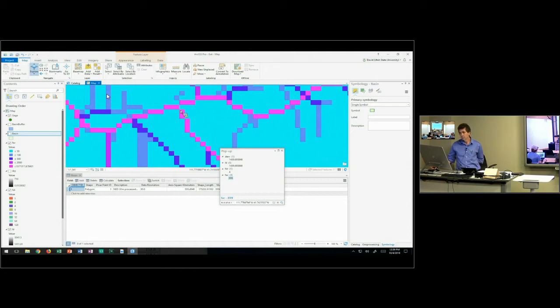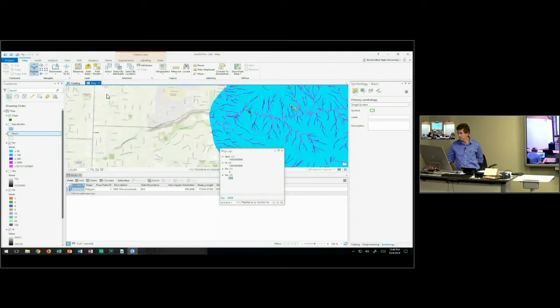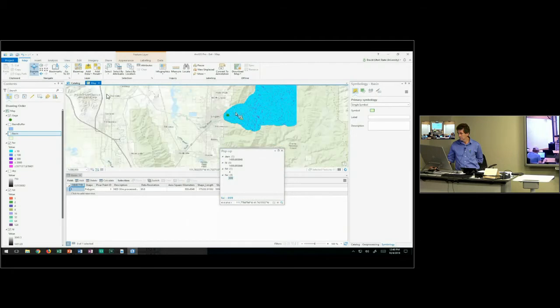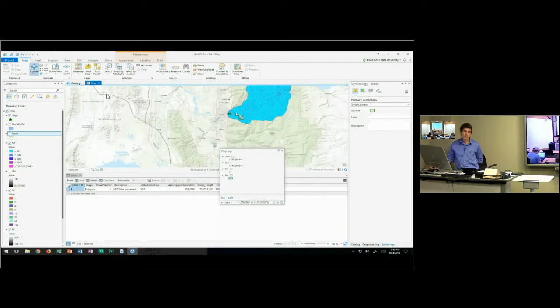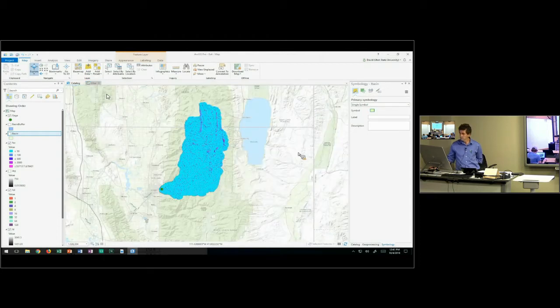This capacity to quickly understand how large the drainage area above a place is, is really, really critical. We have a Texas Medical Center in Houston that got flooded in Tropical Storm Allison, with millions and millions of dollars in damage. And we've got a medical center being built here in Austin, and you think, oh wow, right next to a creek. But when you look upstream, there's only a small drainage area there. The medical center in Houston drains from way out in the western area of Houston. So flow accumulation really matters when you think about locations and flood risk and what's next to these rivers.